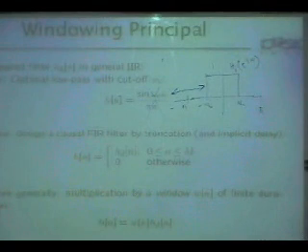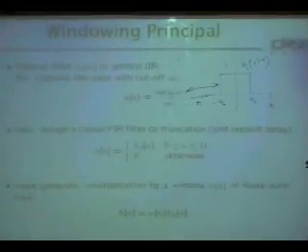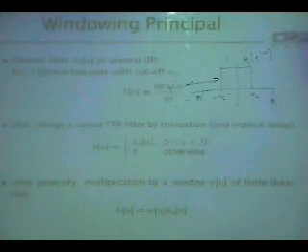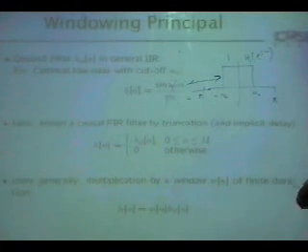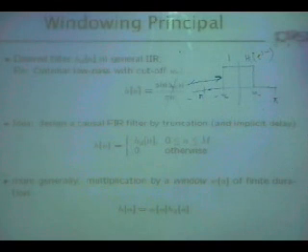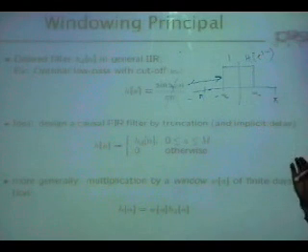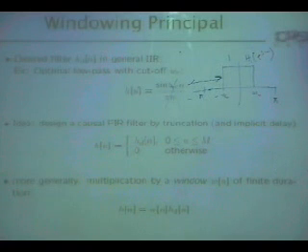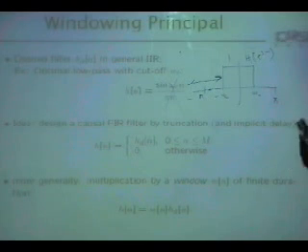about it. Either you design other types of IIR filter, which we have seen, which are realizable, because you get a closed form expression in Hc of s. You can convert them into H of z and then to a difference equation. But this cannot be converted into a difference equation. There is no s in it. Okay, so it cannot be put in a closed form in Hc of s, which you convert, or it is stable as well and all that.